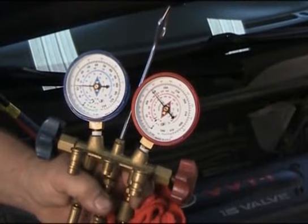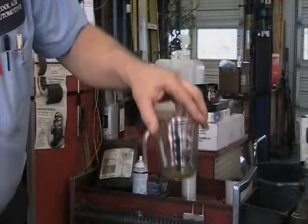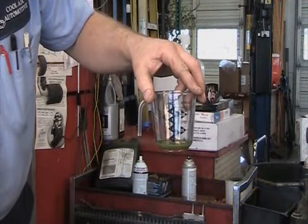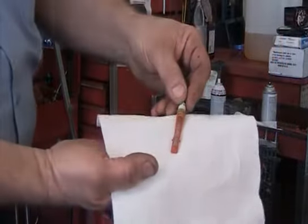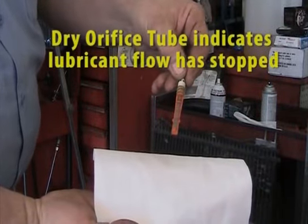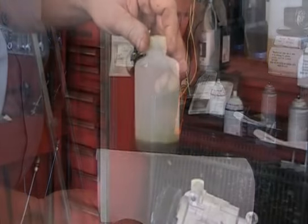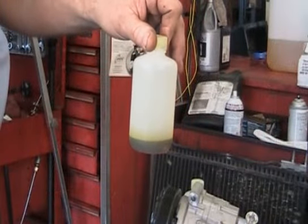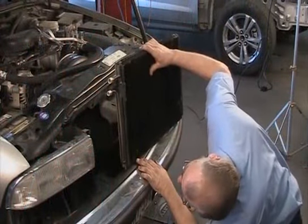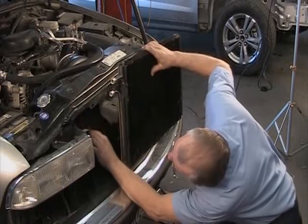System recovery will indicate a low charge. Draining the compressor lubricant and getting 1 to 2 ounces will be confirmation of failure due to lack of lubrication. The orifice tube in these failed systems will normally be very dry, indicating normal system lubricant flow has stopped. Once again, the contaminated condition of the compressor lubricant indicates the system requires flushing to remove the remaining 4 ounces, and a condenser replacement on 2000 and later models.